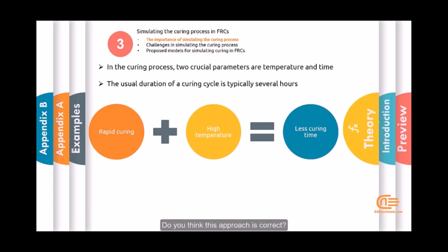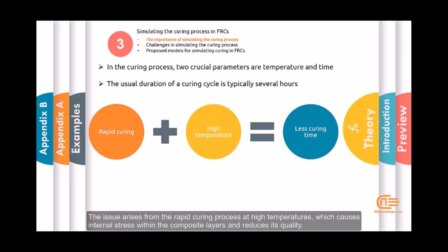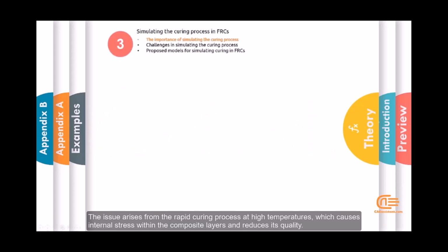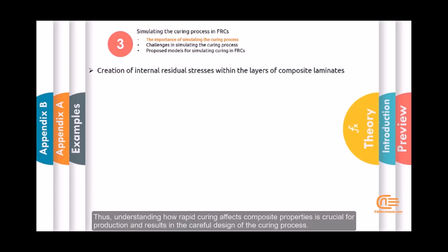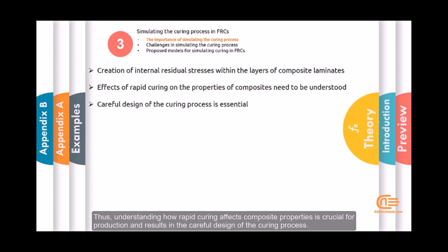Do you think this approach is correct? The issue arises from the rapid curing process at high temperatures, which causes internal stress within the composite layers and reduces its quality. Thus, understanding how rapid curing affects composite properties is crucial for production and results in the careful design of the curing process.